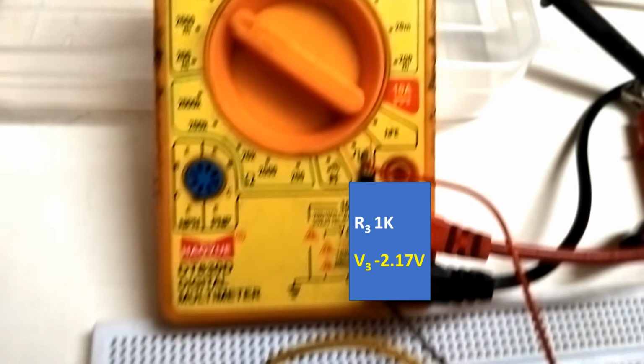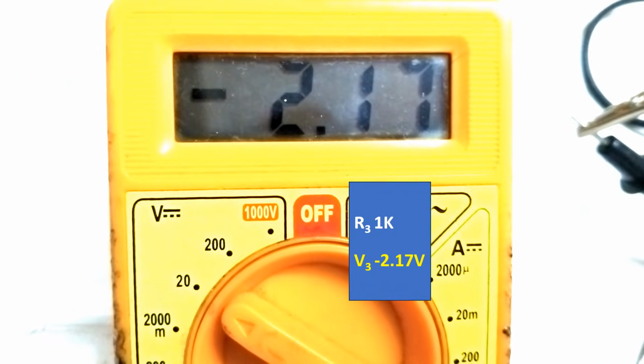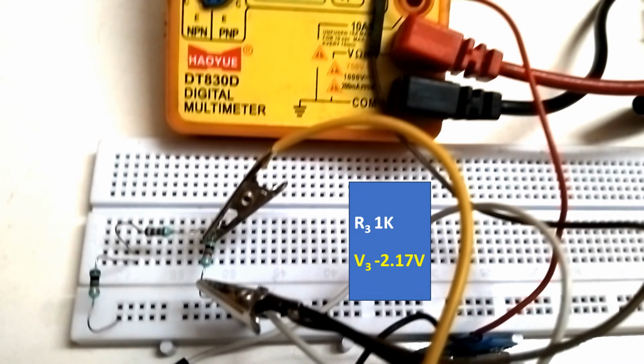The third 1 kilo ohm resistor, the potential difference is 2.17. That is almost similar to the first resistor. So if you sum all these negative values of potential differences with the positive value of the power supply battery, then again you get almost zero, taking into account the measurement errors possible.